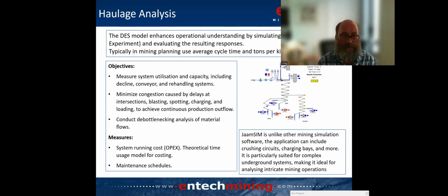So what we're dealing with now, and what I'm doing at the moment, is integrating conveyor systems into the mine. We're integrating in some fashion, but mainly conveyors. And then you've got another problem: how does the haulage system interact with the conveyor system? Because you still need trucks to get to the crushing bay with the conveyor crusher before the material comes to the surface.